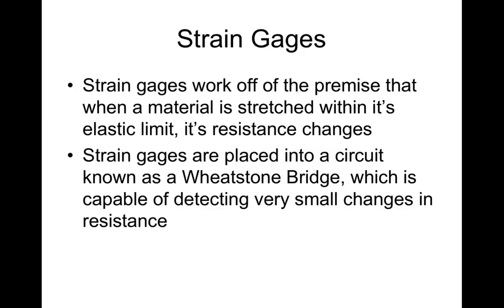And because the change in resistance is going to be very small, basically we take the strain gauges, which are effectively acting as resistors, and we put them into a circuit known as a Wheatstone bridge. A Wheatstone bridge is actually a circuit that's capable of detecting very small changes in resistance.